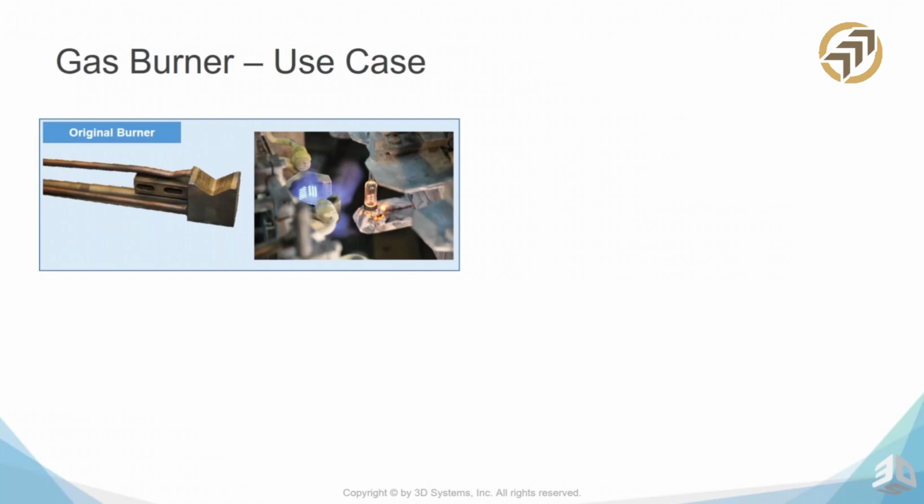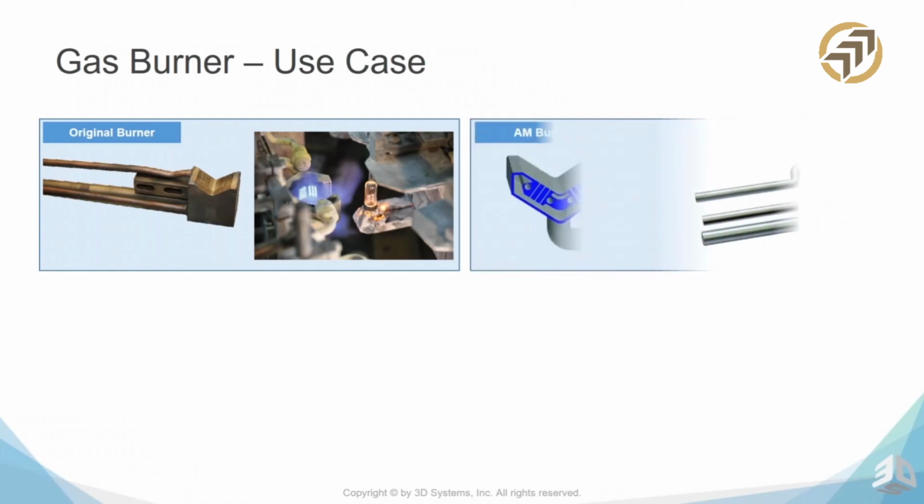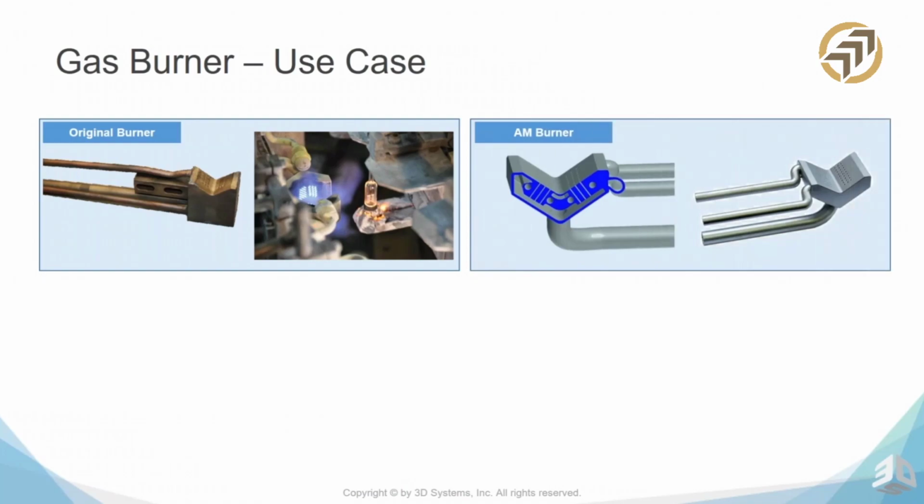So for example, the purpose of these burners is to pinch glass. Their purpose is to distribute flammable gases as uniformly as possible through the small nozzle holes. To make sure the nozzle holes don't deform because of the high temperatures, the burner is cooled using an internal cooling system. Due to insufficient cooling accumulated over several months of non-stop operation, tube attachment failed on the sealing plugs, or drill cooling holes came off. Obviously, fixing these issues required lengthy and costly repair actions, which basically stopped the production line. So to reduce the downtime, a new cooling system was required.